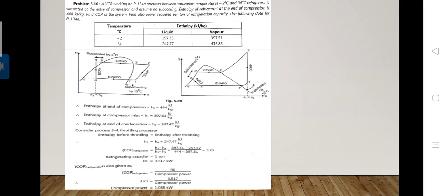So the vapor coming out of the evaporator is allowed to stay for some more time in the evaporator to ensure dry saturated or superheated vapor at evaporator exit, thus increasing the temperature of refrigerant vapor more than the saturation temperature in the evaporator, that is known as superheating.